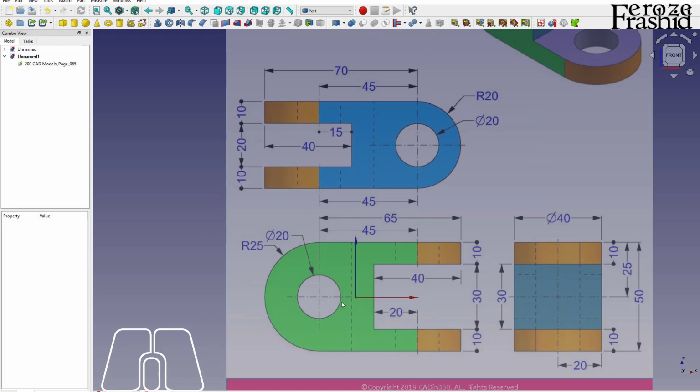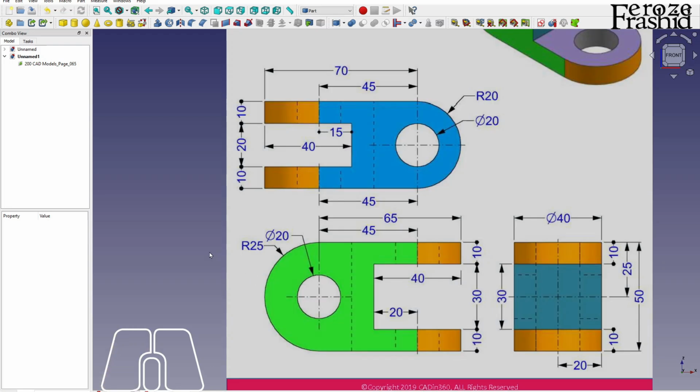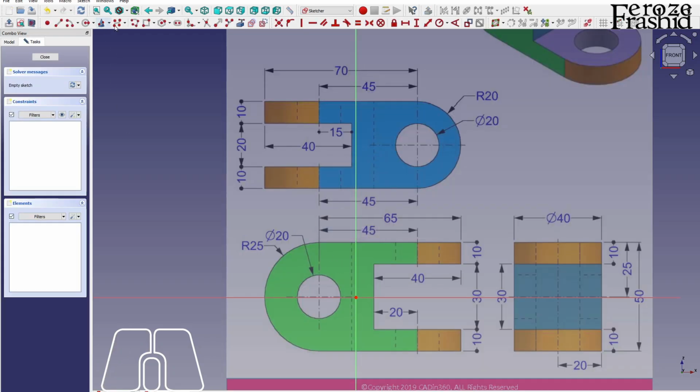Now I want to trace only the left side of this axis cross. That's what I want to do on our front sketch. So it will be on XZ plane. That's where the image is. And I want to trace only the left side of this image.